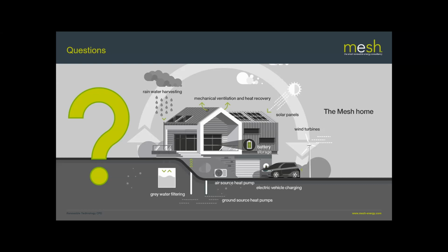Daniel made a comment about using fan-assisted radiators such as Dimplex Smart Rads for cooling. Just be careful, because I'm not sure whether the Smart Rads, no, the original Smart Rads weren't cooling compatible because they didn't have condensate drains in them. They were heating only, but I think they do now do a heating and cooling version. So just be careful with that one.